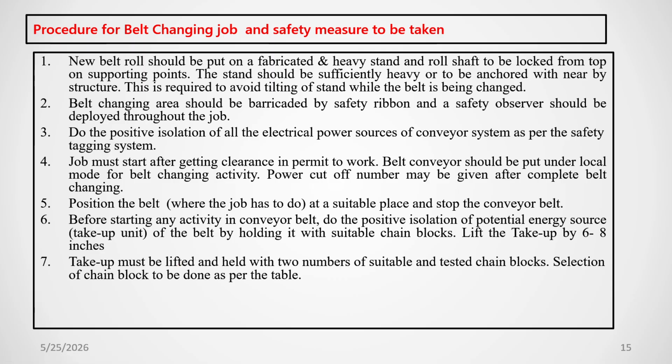And you have to ensure that it is properly rested on the chain pulley block or on the angles or channels, whatever may be. The take-up must be lifted and held in two suitable tested chain pulley blocks. I have already discussed the size of the chain pulley block. Selection of the chain pulley block will be as per the table.